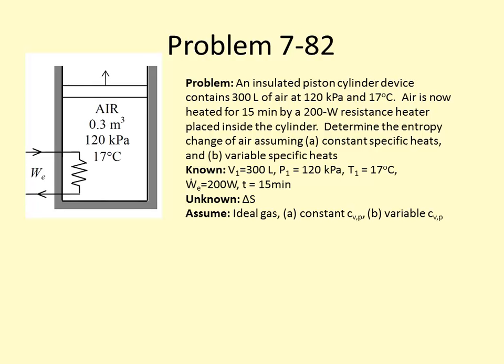We're assuming a constant average specific heat, but we don't know the final temperature. Luckily for you, I know the final temperature, so I'm going to assume that our constant average specific heat is evaluated at 450 Kelvin. Why would we do that? You could just write C sub P as a function of T2 though. But I need to solve this equation.